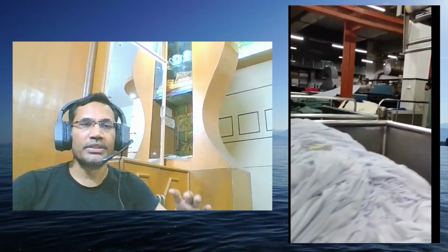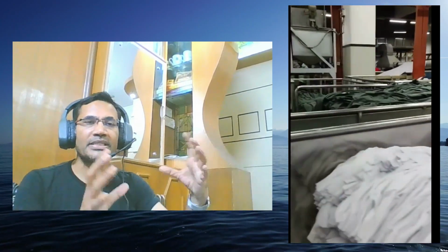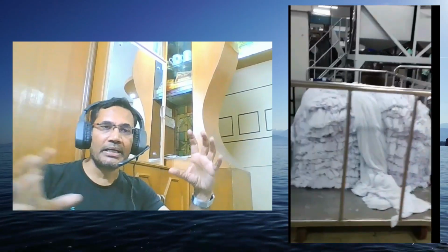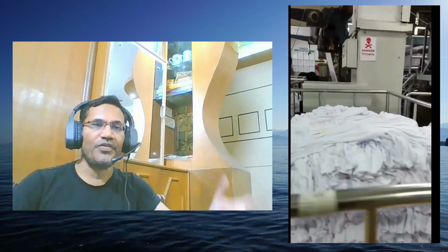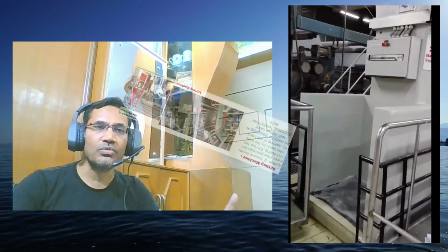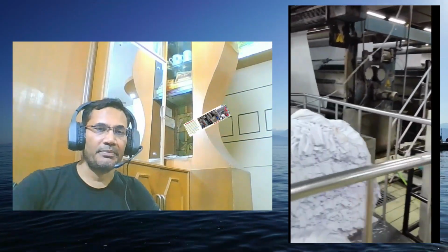After dyeing there may be excess water that also has to be removed from here. Then the fabric is cut for untubing or for opening. That part is actually taking place here. Again, squeezing, removal of excess water, slitting, or cutting the tube fabric to untube it.